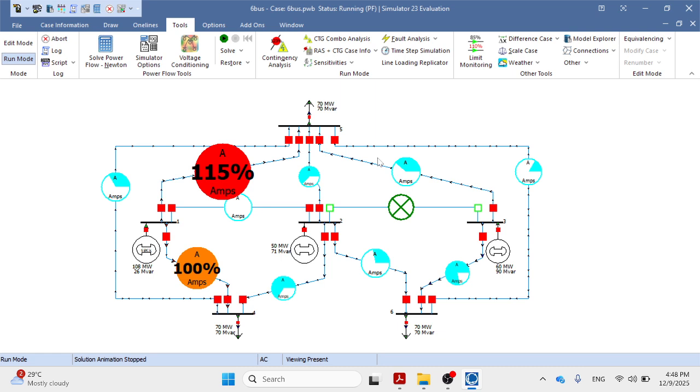For lab 2, our challenge was the overcurrent relay, since we have 4 overcurrent relays and a transformer. But for the final project, it comes to the distance relay, since we have different in-feeds. So you have to consider the different scenarios and find the worst of the worst. The worst of the worst is the one with the biggest K, so that one no need to be considered. The smallest K must be chosen. This is the hint to help you.